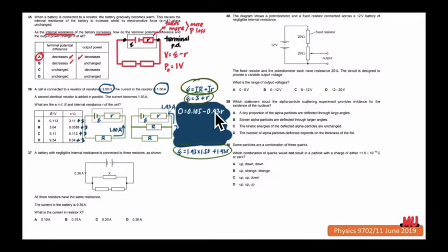Then, this R minus 1.93 R or negative 0.93 R. Internal resistance R therefore is 0.105 divided by 0.93 or 0.930, which is 0.113 ohms here in this option. The EMF is that added to 3, which is this. Alright, C is the answer.